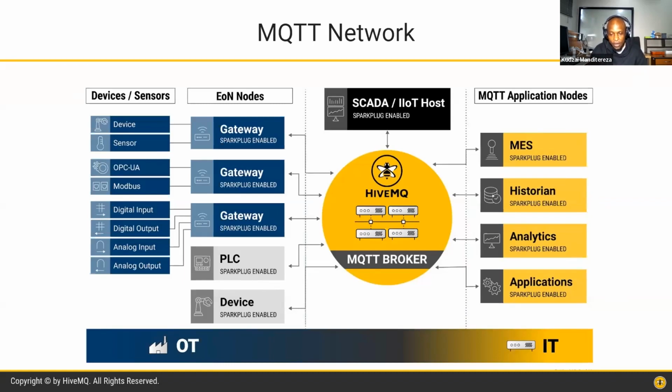The job of the broker in this case is to filter all incoming messages and distribute them correctly to subscribers. So essentially, all direct communication is totally removed, thus making it easy to merge data from control systems with IT systems in the cloud without them having to know anything at all about each other's implementation details.